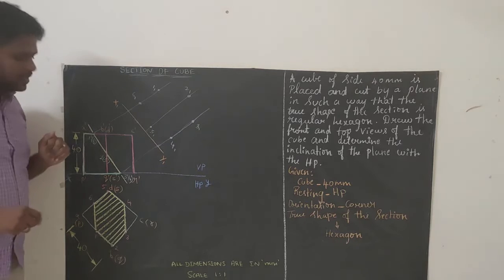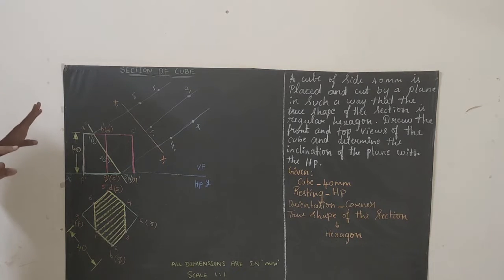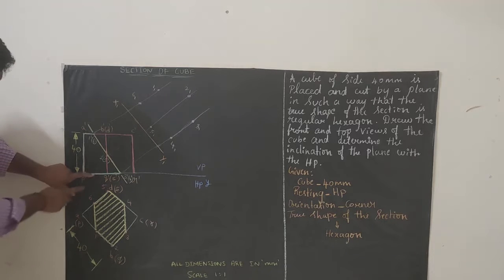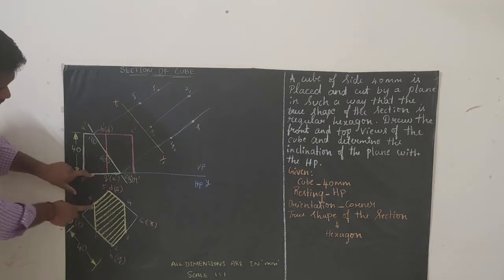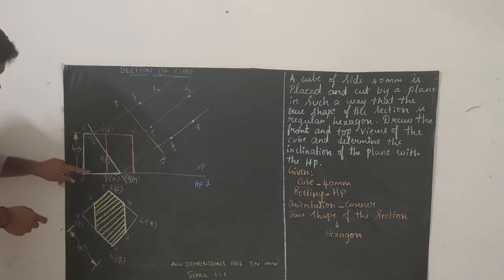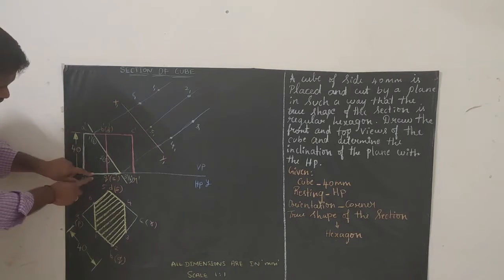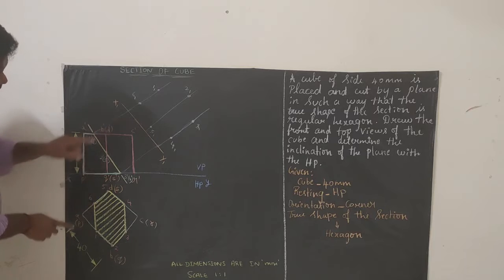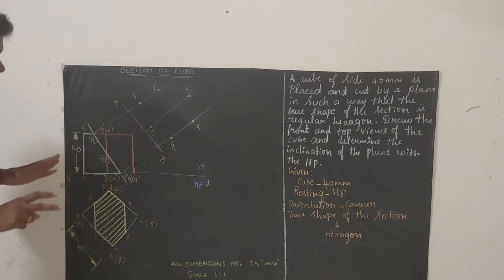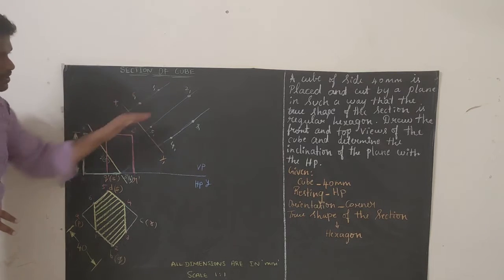Okay, so next thing is, take your compass. Keep your compass at the reference line. Measure from the reference line till here. Keep your compass on the reference line and measure from the reference line to 6. And I forgot to tell one thing: you have to extend all these blue lines.